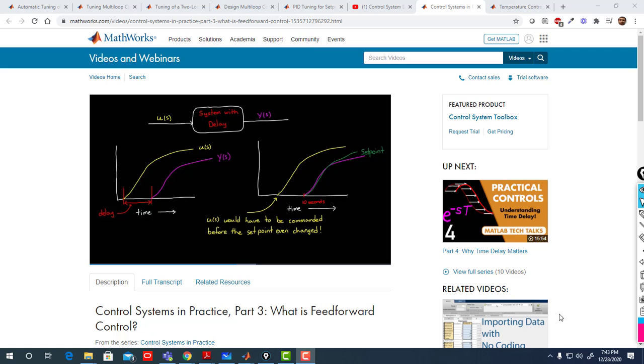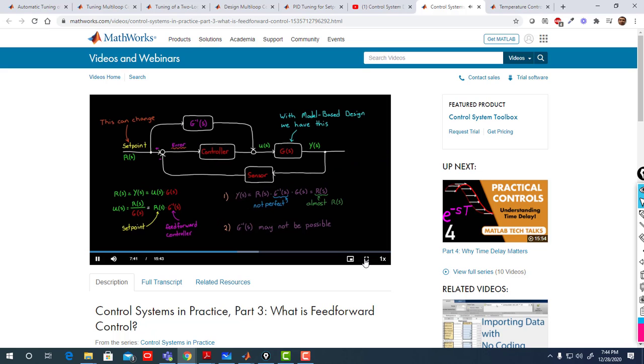Well, for feed-forward control, I also recommend watching this video. It explains the feed-forward control well, basically what we said, but in addition something new, which we'll see now. Rather than invert the dynamics exactly, we usually try to fit a causal and realizable model to the inverse. So here they are basically talking about the feed-forward controller design.